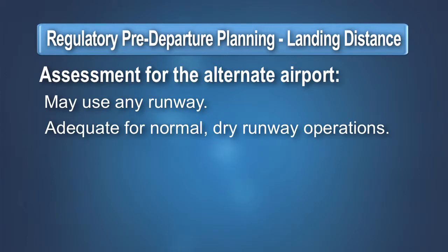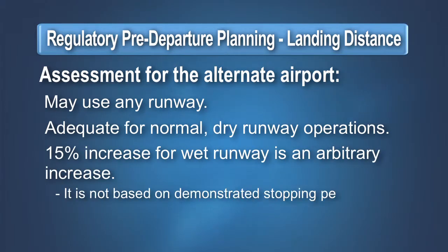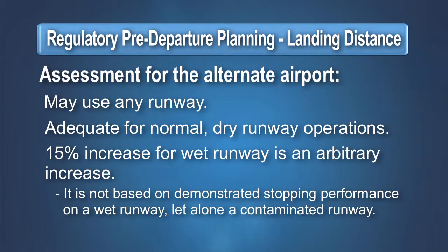This evaluation is adequate for landing performance planning for routine operations when the runway is dry. The 15% increase required when the runway is wet or slippery is not based on demonstrated stopping performance, but is an arbitrary additive applied to the dry runway factored landing distance.